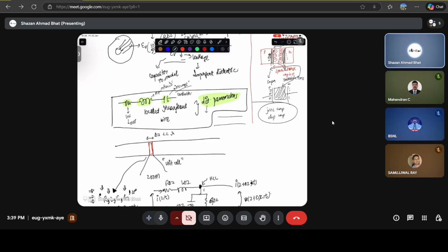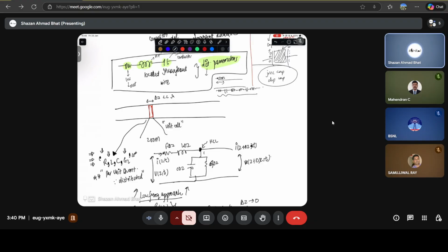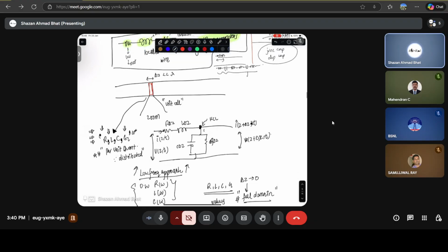So for example, if this is a wire, you cannot say that the resistance, inductance, and capacitance are only in this region. No, it's basically in the entire region. These are basically modeled as a lot of inductors and capacitors in consecutive fashion. So this is entirely distributed throughout the region. And now if you have inductances and capacitances throughout the region, most of the time it's something like this.